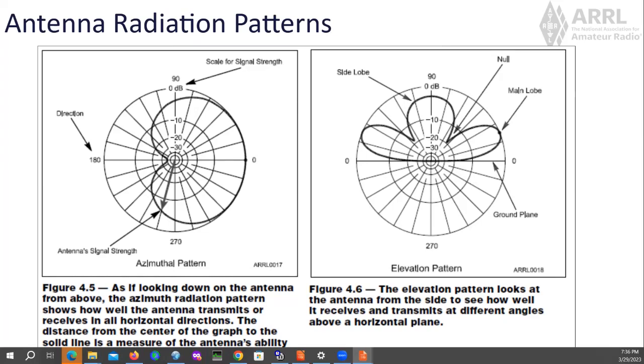There are also times when you're trying to work a station and you have interference that you're receiving. Oh, yeah. Okay. And if you turn your antenna so that the notch on the left is in the direction of the station causing you interference, you can minimize the interference in your receiver. Oh, which is also a really good point. Yeah, quite useful.